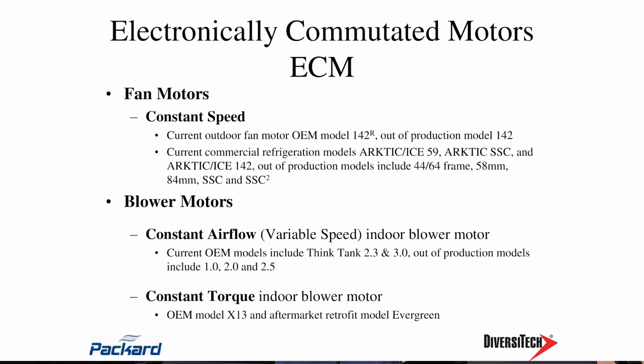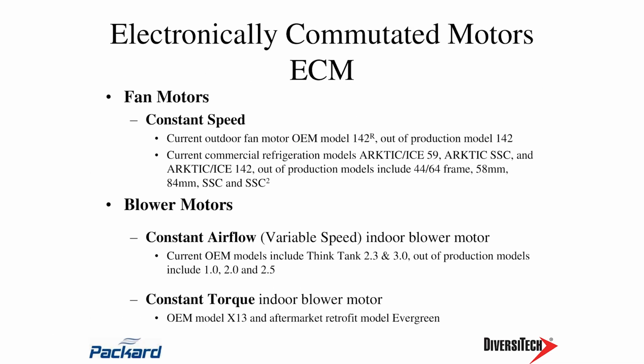But on ECs, I can design it more specifically if it's being used with a fan blade or if it's being used with a blower. Well, why is that? Because they react differently to the static pressure. And so now we can design them and take into account what's going to happen to them as we put them in a load, whether they're used in a fan or in a blower.